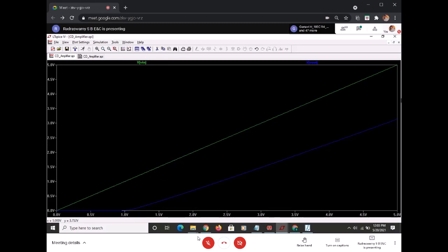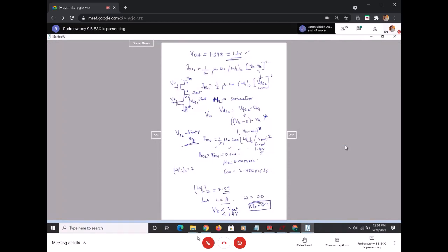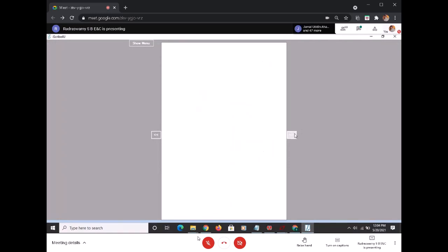After 4 volts onwards, you can see that some kind of parallelism is coming. Now we can consider voltage 4, 3.8, 4.2, all these as the biasing voltage. That is what we have to understand, or get, from this DC analysis. So from DC analysis, just go to the next one.